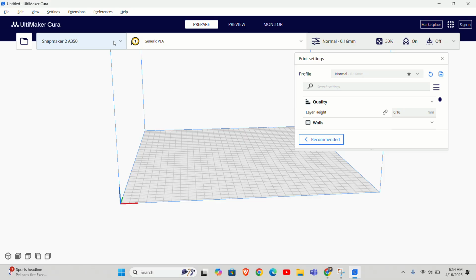So the second step of 3D printing is converting into STL. After converting into STL, we put this STL file in Ultimaker Cura. Ultimaker Cura will convert that STL file to a .gcode file. G code is basically the coordinates of the positions of the machine, because the machine doesn't know what you have to print.